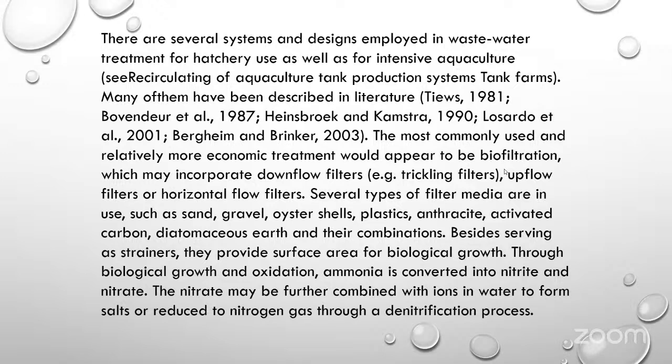Several types of filter media are in use, such as sand, gravel, oyster shells, plastics, anthracite, activated carbon, diatomaceous earth, and their combinations. Besides serving as strainers, they provide surface area for biological growth.